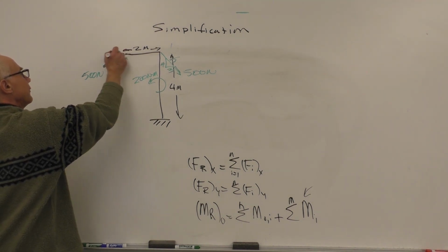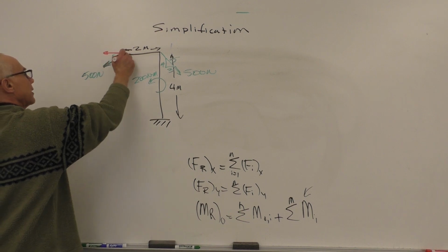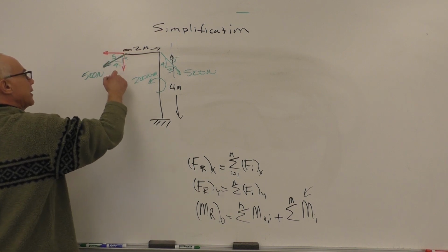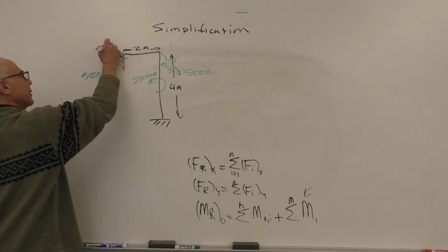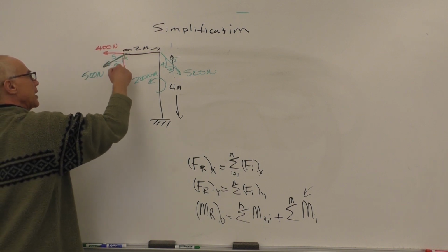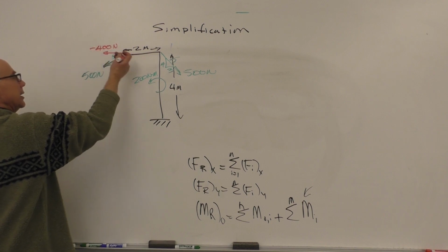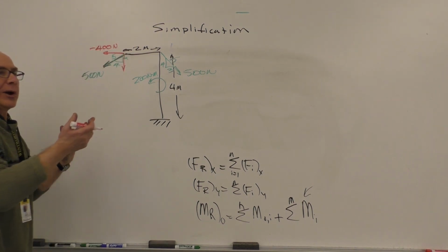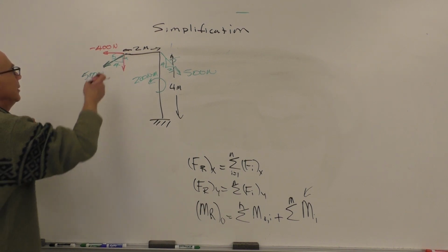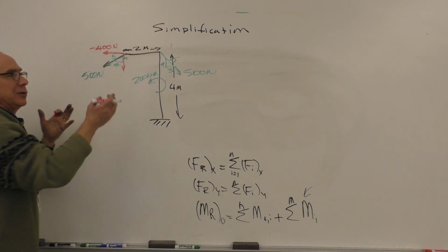So in this case, we're going to have an x component and a y component. The x component is 4/5 times 500, 400 Newtons. And the y component, and I'll put a negative here because it is in that direction, although this is a point of complication to a lot of people. There's like 2 schools of thought.